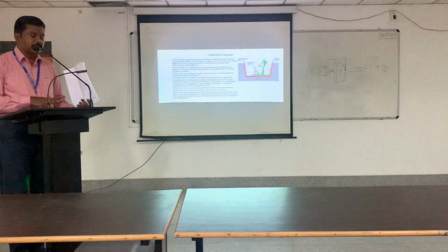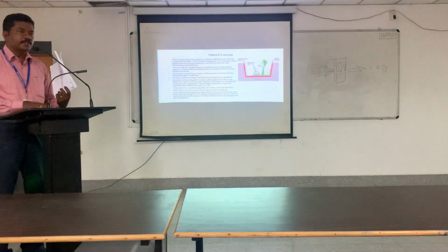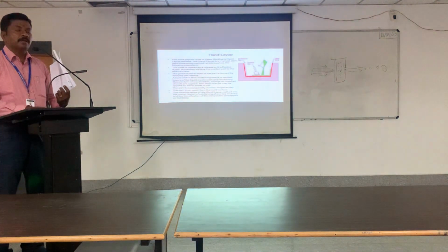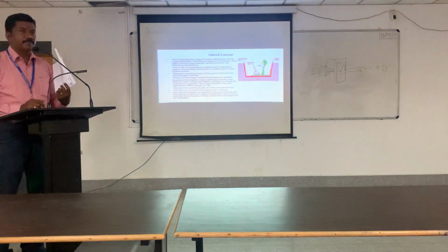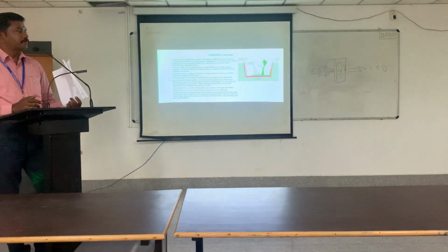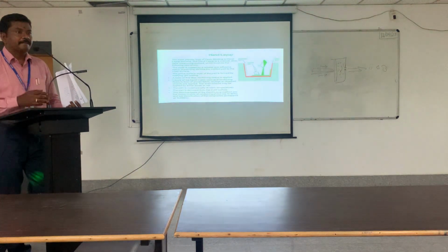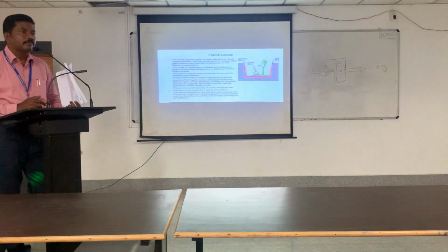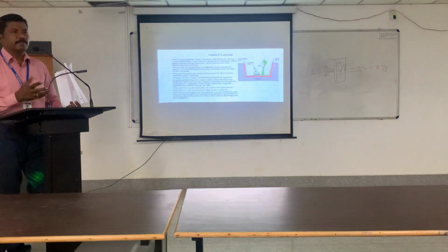So for this, a mold pattern should be taken. A smooth mold pattern should be taken, and on the pattern you should apply a non-sticky agent, either gel or, mostly, turpentine. Wax plus turpentine or any kind of non-sticky agent you have to apply.